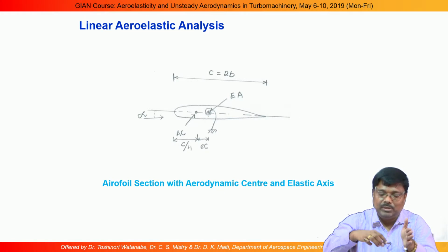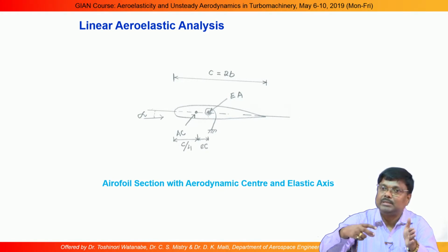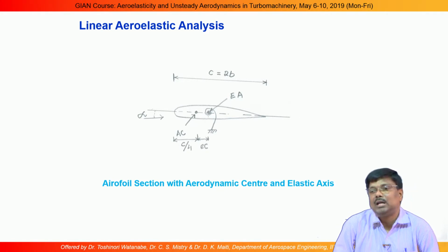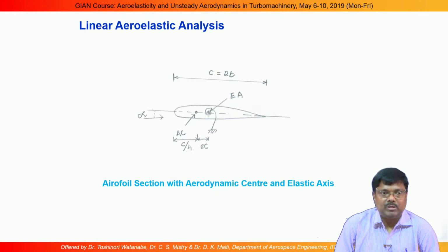The stiffness about the y axis is what we call the torsional stiffness. So, if we look at the equilibrium equation, when lift is acting on the structure, we will have two equilibrium equations. One is the torsional equilibrium equation, another is the bending equilibrium equation.